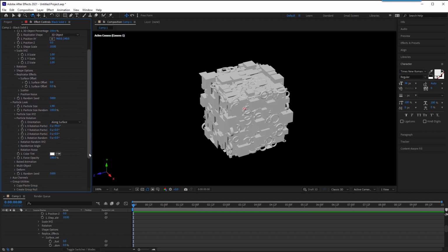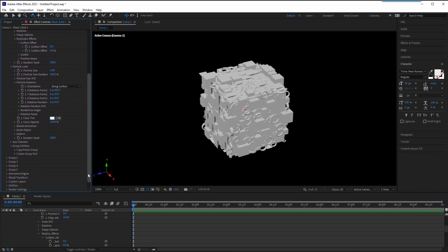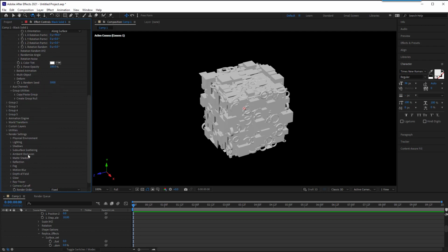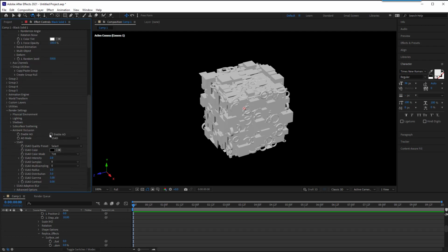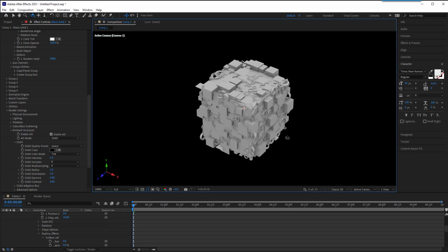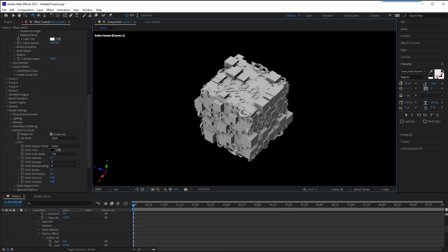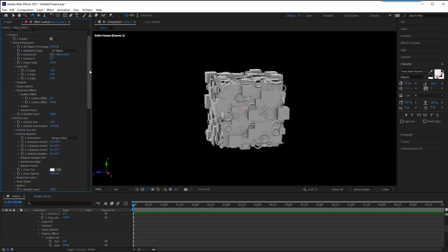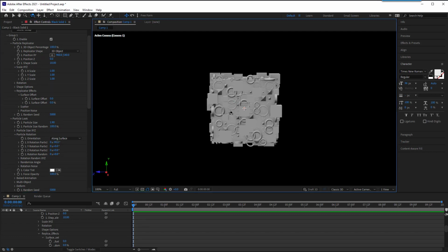But one thing I think is worth noting is that if I go into the render settings here, and I turn on ambient occlusion, right? We start getting stuff that looks a little bit cooler. I'm going to bring up the intensity of the ambient occlusion, and check that out. That's starting to look pretty cool, right? Although I'm looking at this and I see now that the pyramids must be backwards, so maybe I need to go -90 on that rotation. So let's come back here and try -90, and there we go. Now we've got some pyramids.